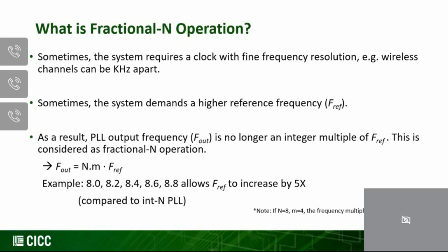Another good reason is that sometimes the system will require a higher reference clock frequency. Sometimes it's because of the choice of the crystal oscillators, and sometimes it's because the system will require you to implement a very wide PLL bandwidth. So for those reasons, sometimes the reference frequency can be high.